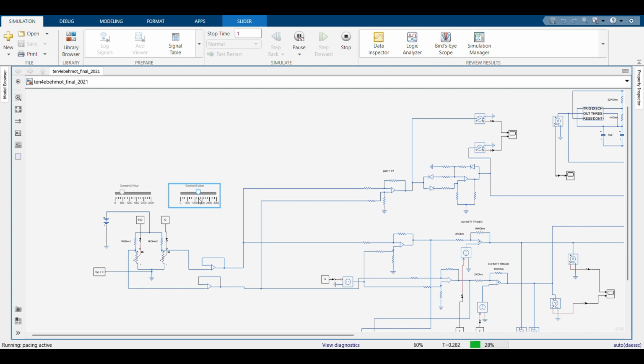change. We are gonna take the difference between those two voltages, pass it through an absolute circuit, which is gonna take the absolute value of the difference between the two voltages resulting from the two voltage dividers, and it's gonna pass this positive signal. It's gonna be only positive. It's not gonna be negative because we have passed through this absolute circuit.